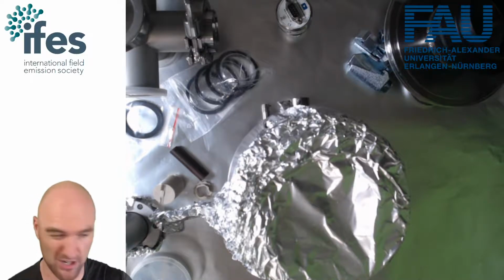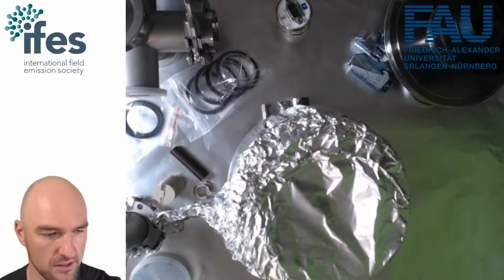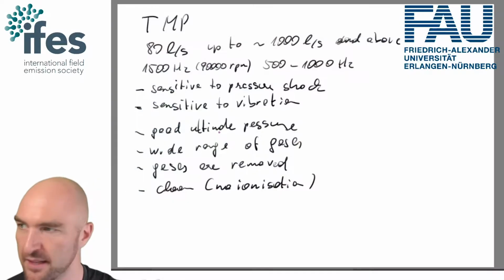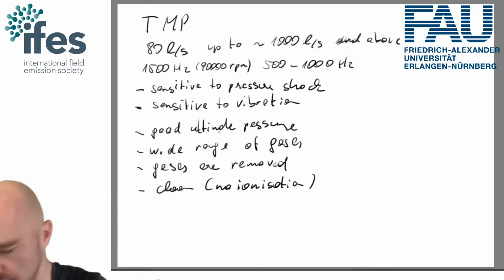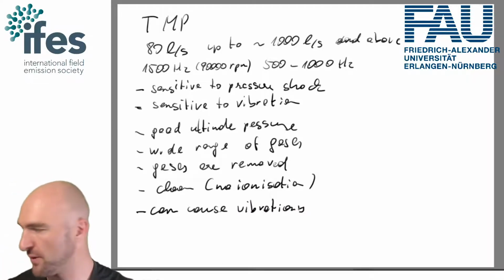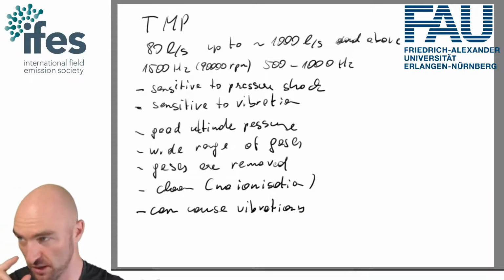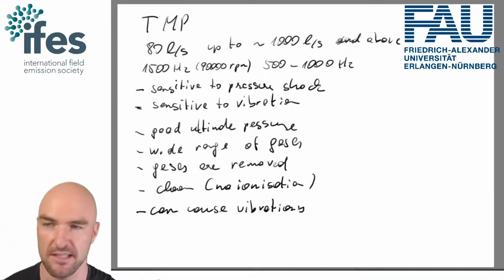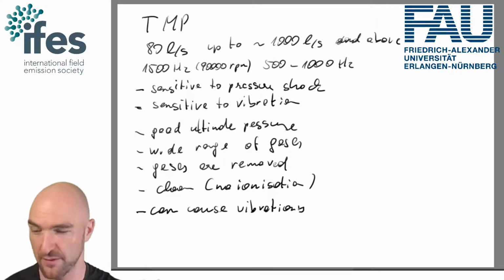Which leads me to one last problem that I've forgotten to mention, and that is that turbo pumps can also cause vibrations. So if you have a system like an atom probe with a very small laser spot size, for example, and it can't have a lot of vibrations, then turbo pumps can cause problems.